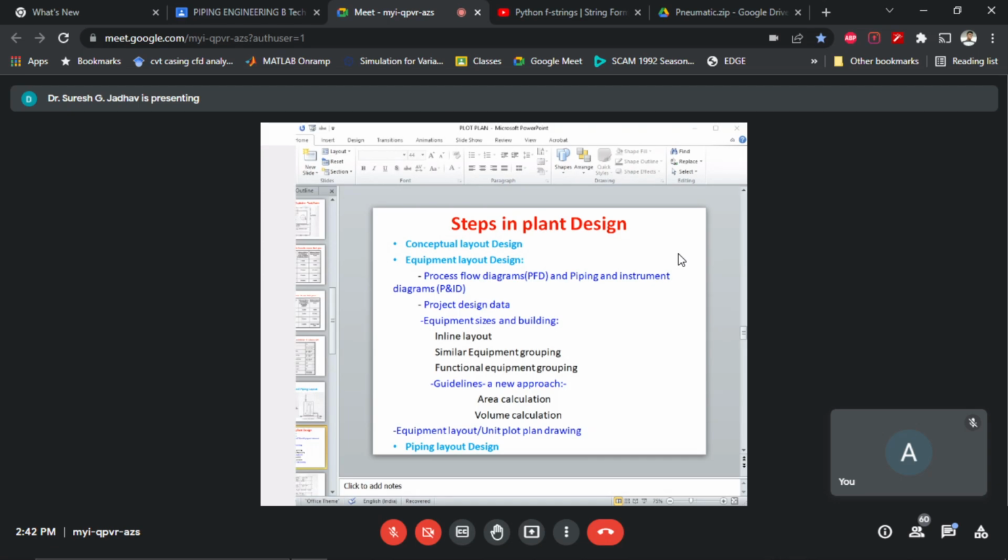P&IDs, piping and instrument diagrams, indicate information such as solid handling, gravity feed, line slopes, loop size, venting and draining requirements, and special piping materials, which govern the equipment location to a great extent. Utility flow diagrams show the individual service lines and utility headers.